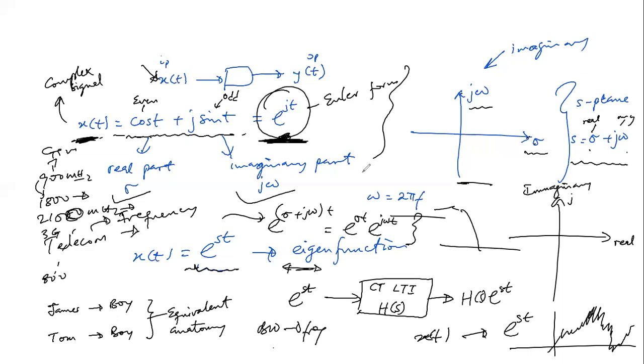So in the frequency domain, analysis is made easier. There are a lot of factors to consider, coming from what we want to do, what we have to deal with, and the ease of analysis. For ease of analysis, rather than doing convolution in the time domain, I would move to the frequency domain where I just multiply those values.